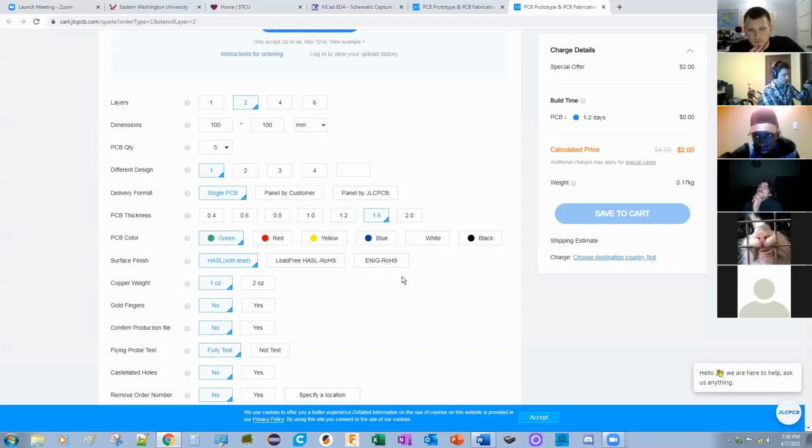But it's a pain to get rid of the copper in spots where you don't actually want it. You have to peel it up with an X-Acto. But for really quick turnarounds, there's no waiting. You just pop the Gerber in and make it that day.